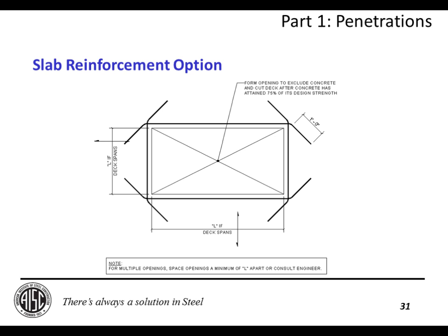So in this case, the cracks are emanating out from the corners of this member. So you can either use a straight bar that is oriented 45 degrees, such as a straight bar right here, here, and here. In this case, you get the best of both worlds because we're providing some flexural reinforcement along the edges, and then that same flexural reinforcement, when turned and extended out as shown, is also quite effective in resisting this diagonal crack. Okay, great, thank you.